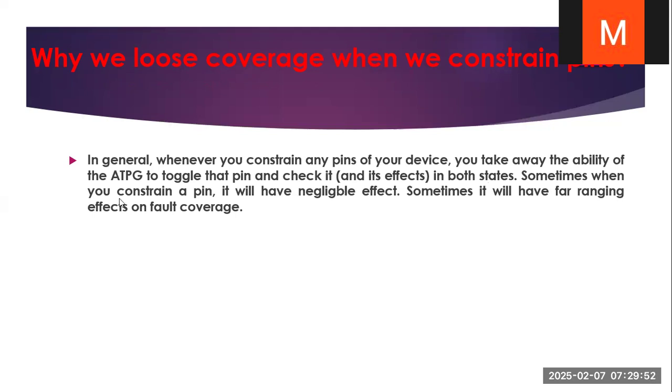Sometimes when you constrain a pin, it will have a negligible effect. Sometimes it will have a far-ranging effect on the fault coverage because that pin is driving a large cone of logic. So if you constrain that particular pin, we can't cover the faults in that cone of logic.